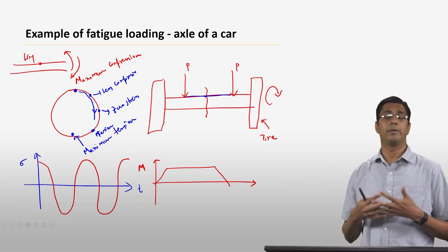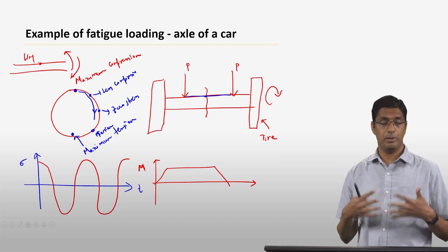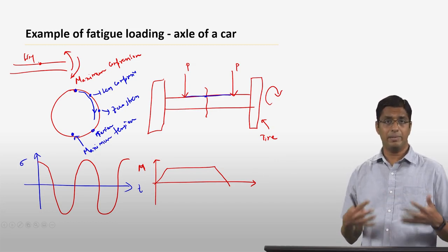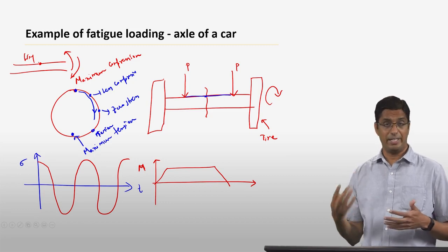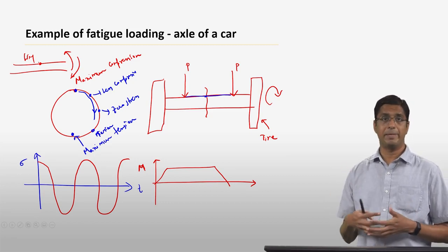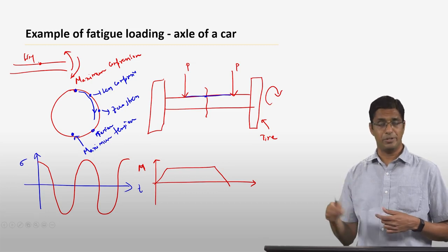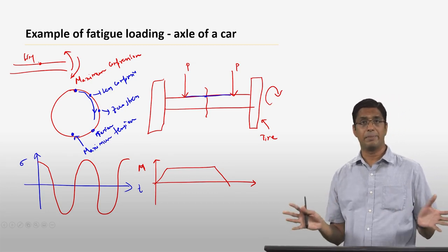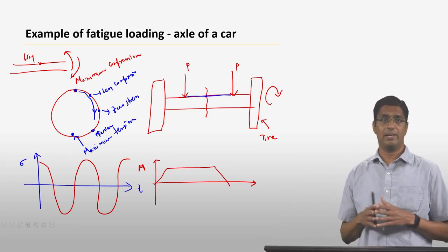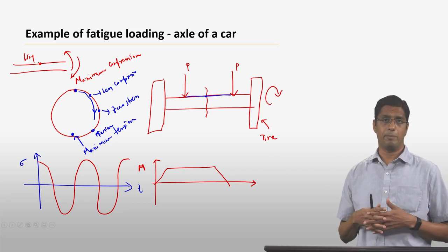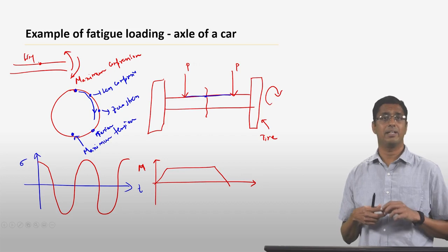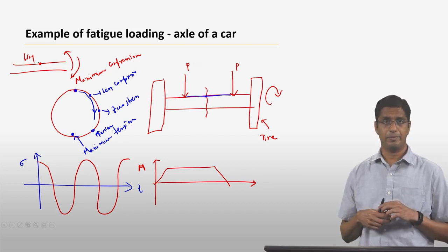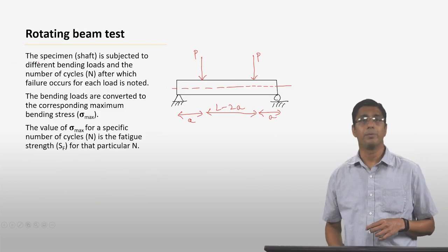So essentially, almost everything that you look at in practice has some kind of fatigue loading, even though it may not be apparent. Okay? The fatigue loading might come because of vibrations in many cases. Sometimes it's because something is rotating. So irrespective of what the actual cause is, many engineering components are subjected to fatigue. And it is this fatigue loading that often leads to failure. Okay, so that is the reason why we need to worry about fatigue.